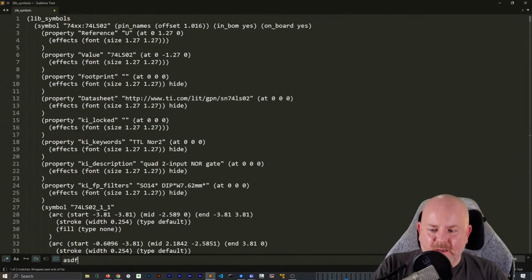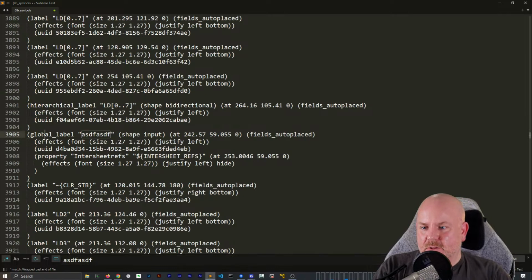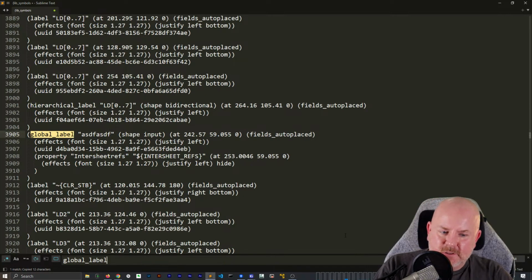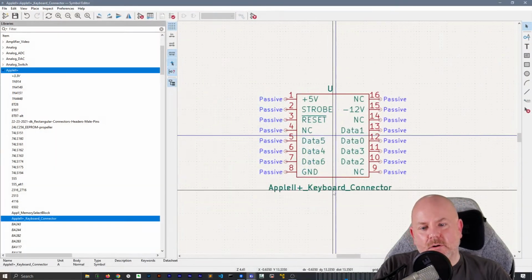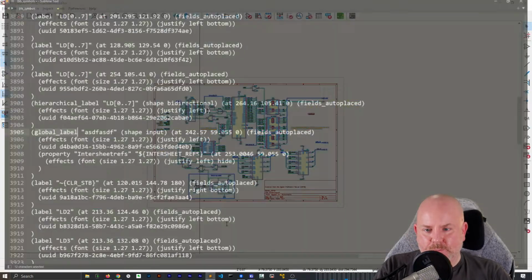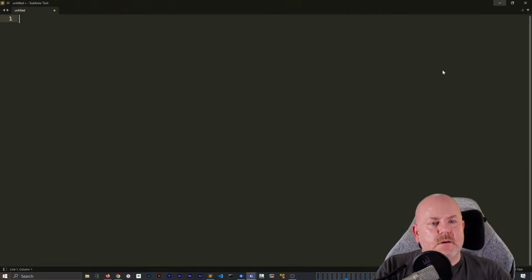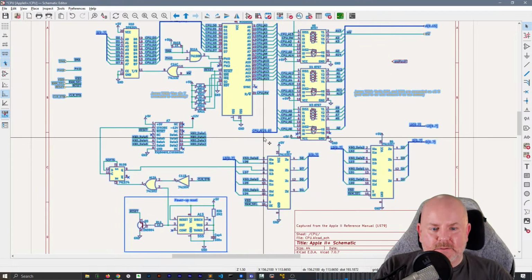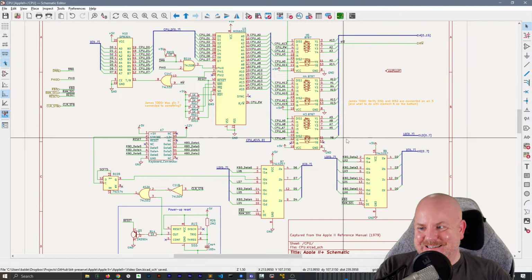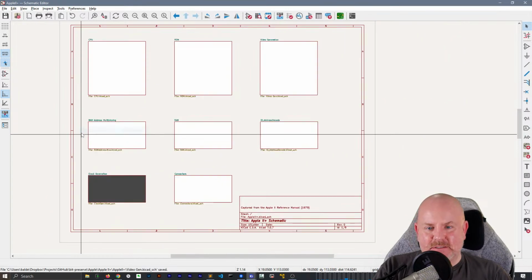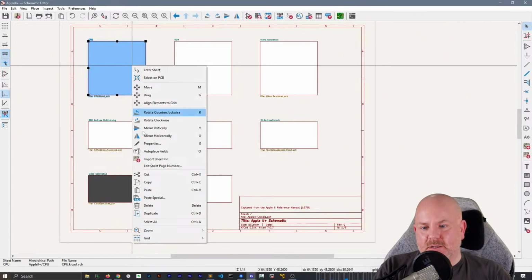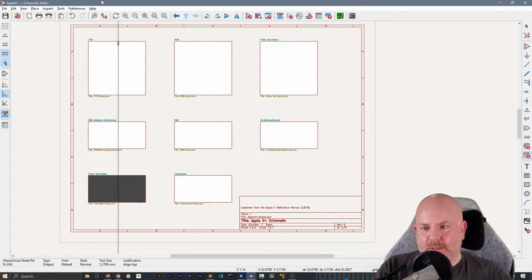Okay, and then I'm going to look for ASDF, and it is a global label. So now I'm going to search this to see, is there a global label? No, we found them all. Cool. That's going to work. I should just leave this open. Okay. All right. So let's save this. And then up here, let's do, what is it? Import sheet pin.